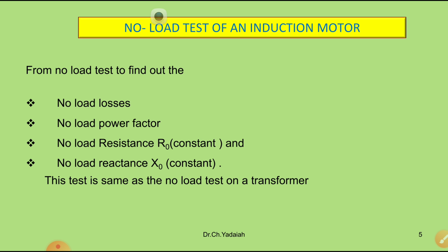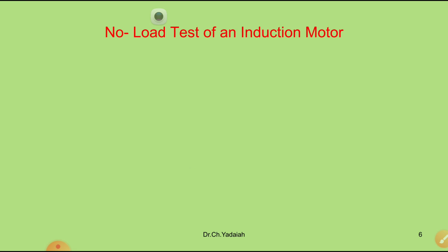The no load test of induction motor, how to do this one? So, we will see. Here, in the no load test, what do the no load losses consist of? In a transformer, there are iron losses and copper losses, but in the case of the motor, there are mechanical losses. Friction and windage losses also play a vital role in the performance of the induction motor.